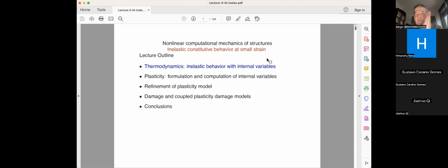So you can imagine presenting now a catalog of different plasticity criteria, which will be the most appropriate for different composite materials. Or the way I took it, I actually took von Mises, and then I put all different refinements, what I call the plasticity model. These refinements are enhancements that you might add in order to increase the predictive abilities of your model. So you can have not only linear hardening, you can have a saturation, that means non-linear hardening. You can have something like kinematic hardening that takes into account a cyclic response.